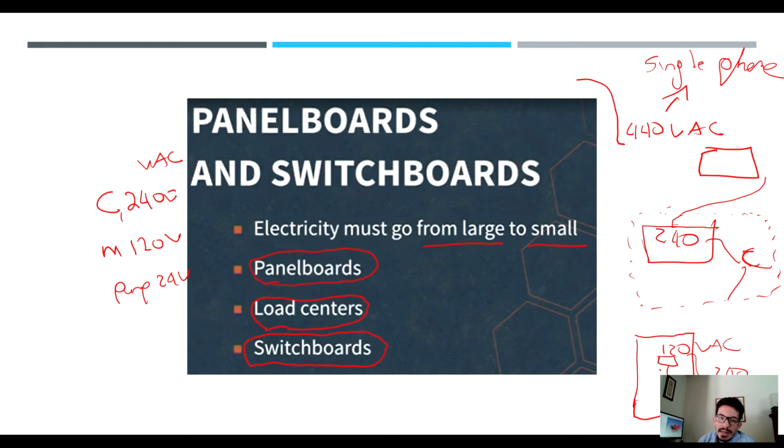And then we need a switch for creating ice or to open a gate or a door or something, which is operating at 24. Oh, a pump. We said we have a pump to push water at 24 volts. So we have another transformer to give us 24 volts. So your voltage is stepping down using transformers. This is a very common practice.